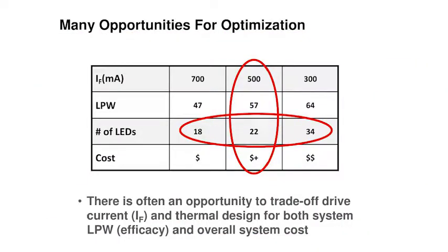In this case, we've done a number of LEDs versus a specific drive current to tell you what that light is going to look like, the amount of light, the cost, all those things. It's just a trade-off. Lumens per watt is basically how many lumens you're getting out of a light fixture and the amount of wattage. Candle power and candela. It's more important in flood lighting and landscape lighting than it is in area lighting, because nobody really looks at those terms when they talk about that.